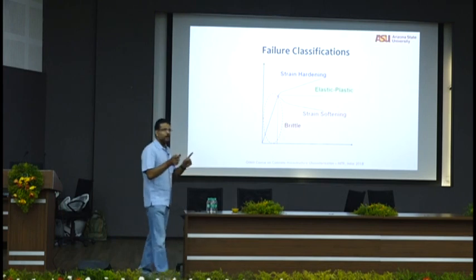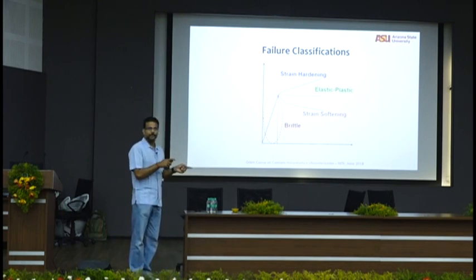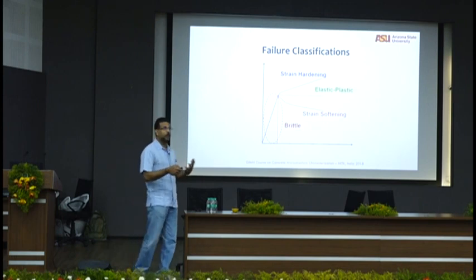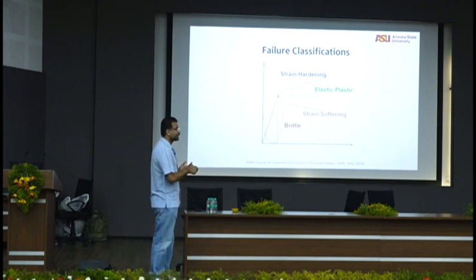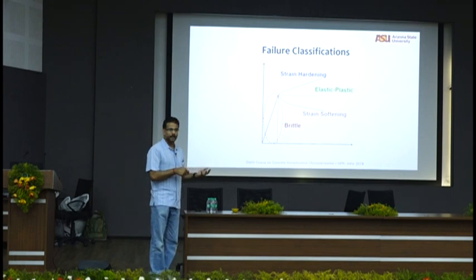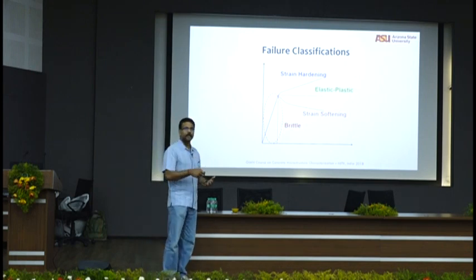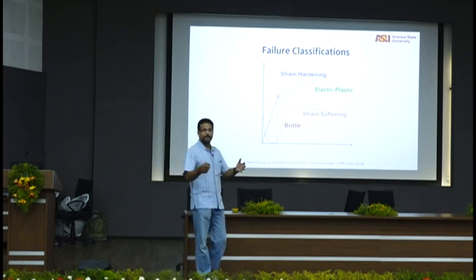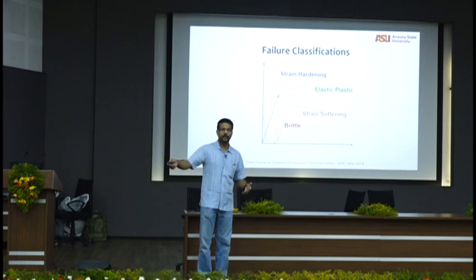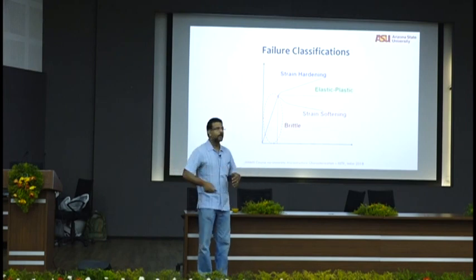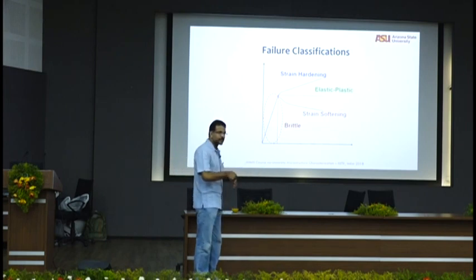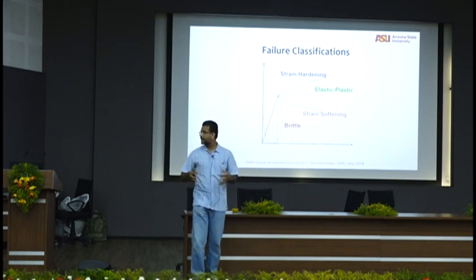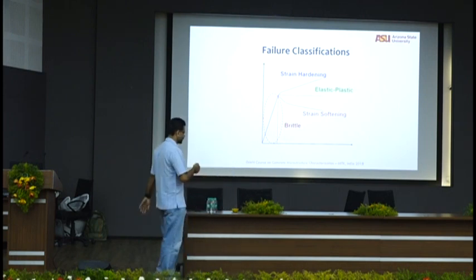So I go back to the materials by design approach. We talked about that, right? Designing the material for a specific function that you want it to do is exactly how this works. Strain hardening. Okay, it's not strain softening, it's strain hardening. You want it to strain harden, or you want it to absorb a lot of energy on impact. Barriers for roads, barriers for planes not to fall over. You want a very strain softening material so that a lot of energy is absorbed on impact.